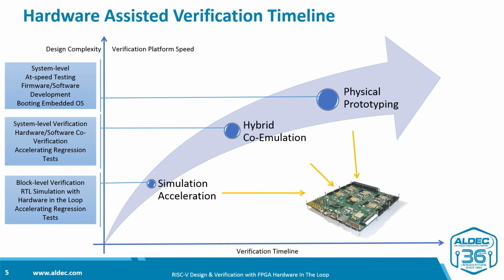Migration towards hybrid co-emulation allows for system-level verification of the entire SoC. At this stage, the FPGA board can be connected either with the system-level test bench in the simulator, or with the virtual platform, or even with the external peripherals. So who will benefit from hybrid co-emulation?